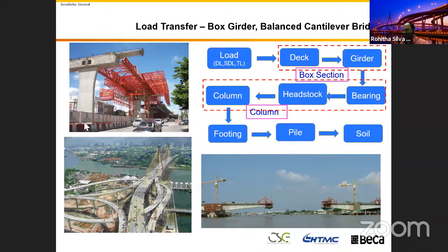In this particular one, we have footings, because the thickness of the column is not large enough to put 2 meter diameter piles, so you need a larger, enlarged area. That's why we need footing, and then to the soil. You can see this bridge is much better.